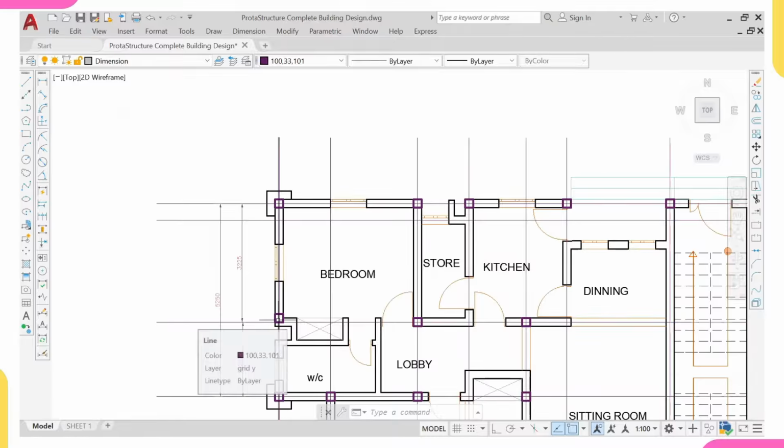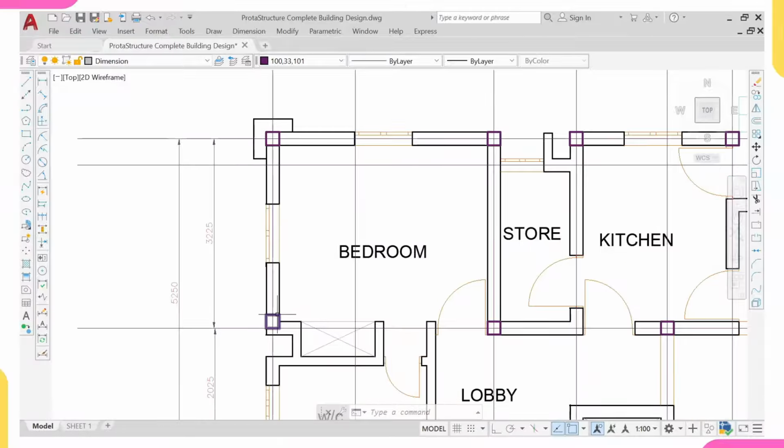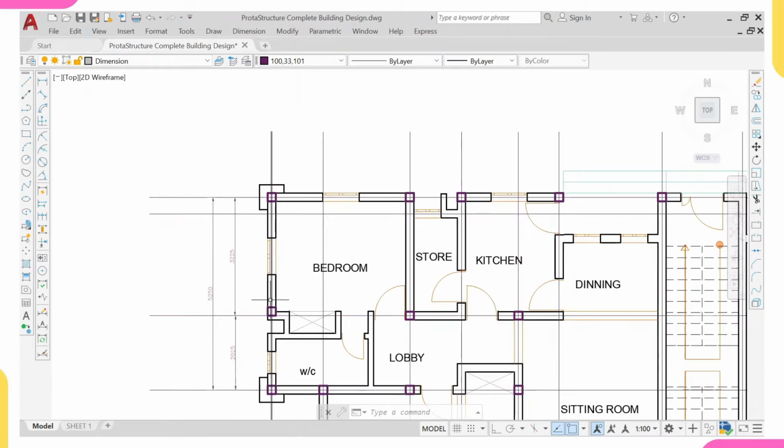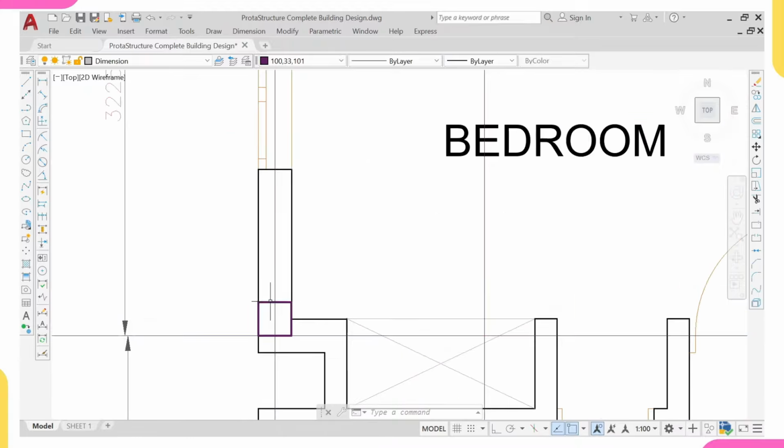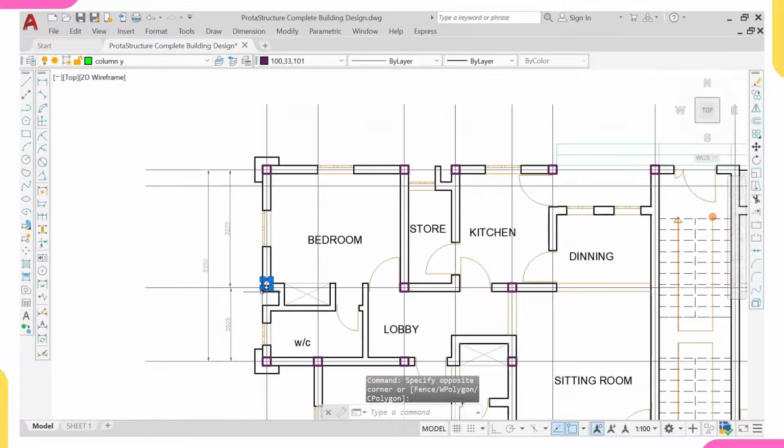And if you place a column here, let me tell you, that means this beam must surely be under 2y16, it is a must. But the thing is that it will be under 2y16, but economy is no longer in view, because if I remove this column and have 3y16, I'm still making profit. Like I'm still having economy in view, because this column now consists of 4y16 and your concrete. But if I'm able to remove this and have only 3y16, that means I did a good job. So these are the things you have to explain to the client, so he will not take you as casual, or just somebody that doesn't know what he or she is doing, because you know that they lack knowledge.